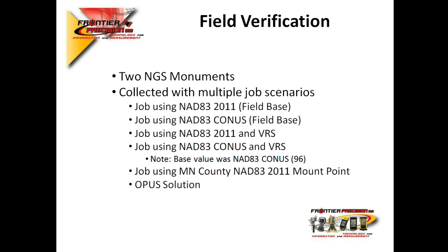We also did one other job, and we collected the information using the 2011 mount point for the Minnesota County VRS, County Coordinate System. So we used NAD83 2011 as our datum choice, and we chose that mount point, and you also see what happens there. And then lastly, we just did an Opus solution just to field verify as well.